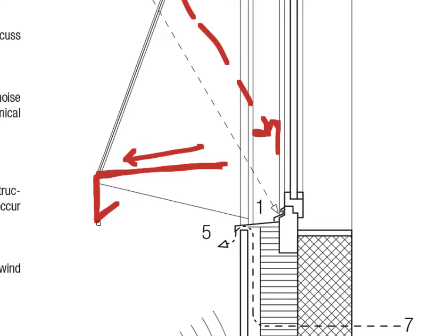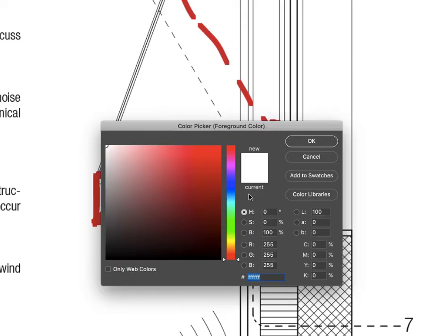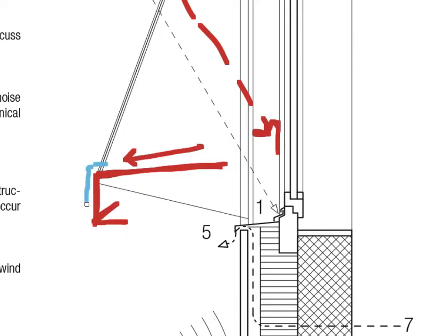And another thing that we notice is that rain water drip. So if it's just a simple metal, or if it's even shaped like this, when you have, let me get a bluish pen for a little raindrop, if rain is coming down here, sometimes it has that capillary effect, and sometimes the rainwater seeps in, and if we have wind blowing from the outside, it might actually push that water inside the construction.